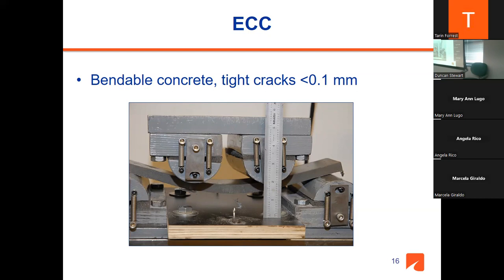Yes. How much of a load approximately is that? When we talk about these systems, we talk about splitting tensile strength and flexural strength. So here is the flexural strength. We can easily get 2,000 psi flexural strength out of it. Regular concretes are more like around 400. This is 2,000 psi flexural strength. So these are very powerful. And then the VHPC is close to it, maybe 1,700, 1,800, the VHPC system. So these are very high quality systems, and we have these systems in VDOT right now.